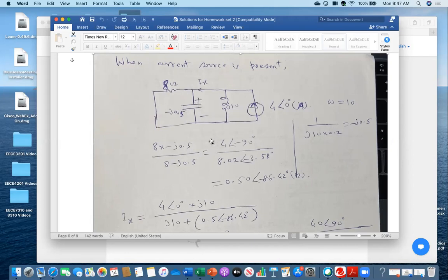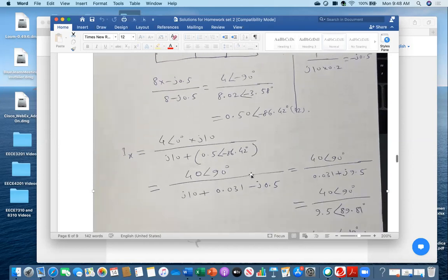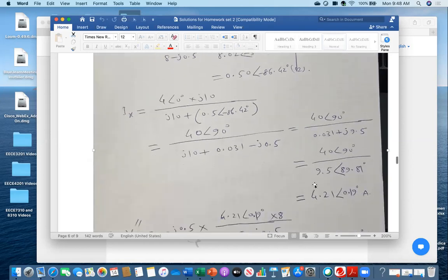So that's why what I am doing, first I am making the parallel combination of these two. You know, these two are in parallel because this is on and this is other branch. So I got this parallel branch, and now I am applying the current divider rule. I want to find out current Ix. I have given the name that this current is Ix. So total current multiplied by this one, divide by this plus this one. And then I got this on my Ix.